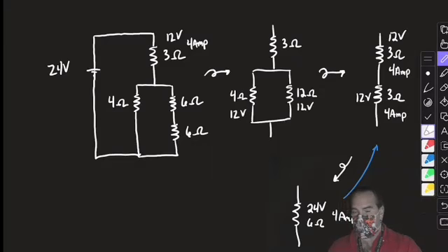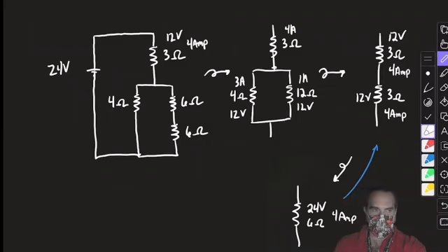Again, Ohm's law to figure out the individual currents. 1 amp, 3 amps. You should be able to note that there were 4 amps there before. By Kirchhoff's second rule, current in has to equal current out. If there was 4 amps traveling towards this junction, there needs to be 4 amps traveling out of this junction, and there is. 3 goes to one side, 1 goes to the other. But that finishes off this resistor,